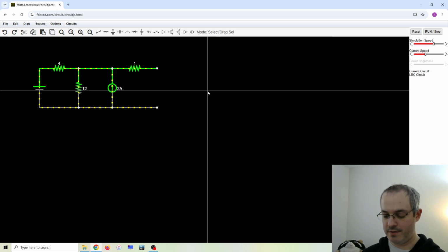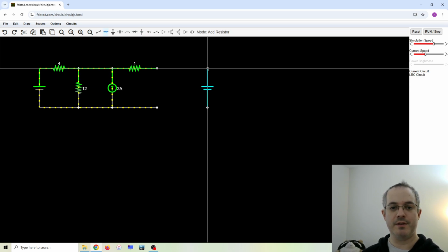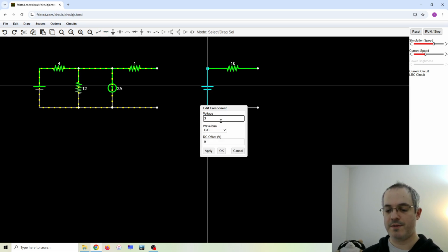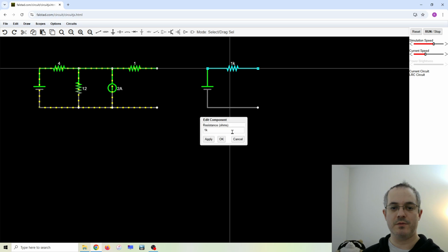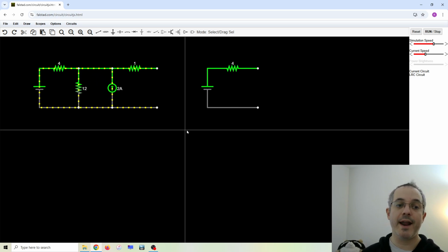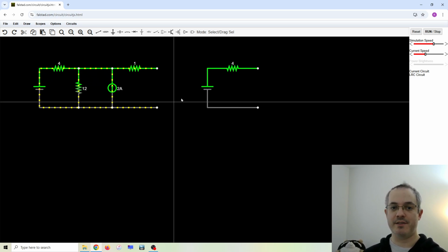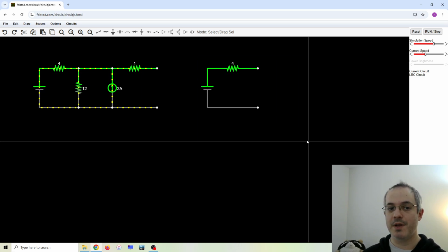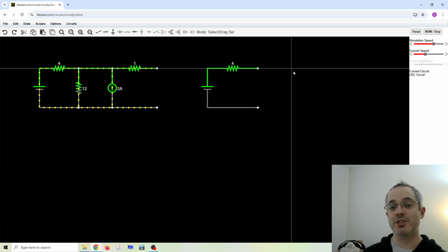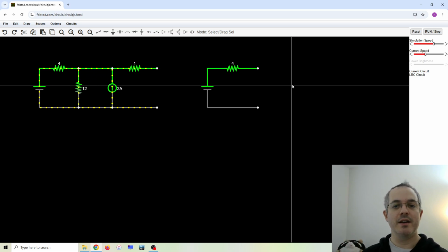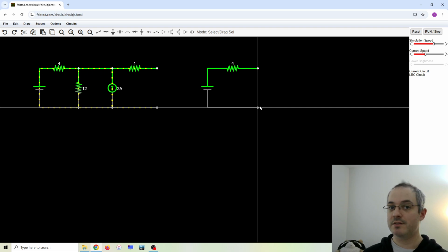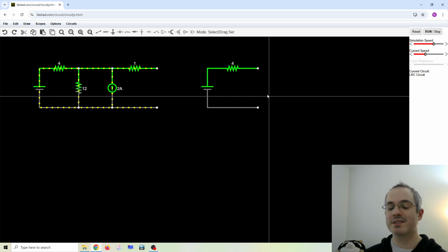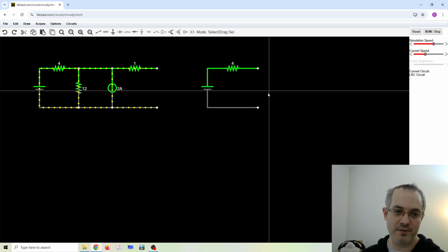And then we said that a 30 in series with a 4 would be the same thing. So let's change this to a 30. Change this one to a 4. Okay, and now remember, when you are checking these two circuits, this one and this one, we're saying they are the same. However, you can't really check it that well completely unless you actually complete the circuit somehow. I recommend just throwing a resistor in. You could use a wire, but I just kind of like the sureness of using a resistor.